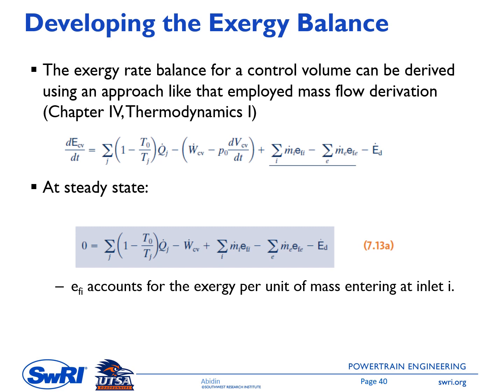on how the mass flow equation was derived. So here on the left side we have the exergy change of the system, normalized by time because this is in terms of rate. On the right side, the first term is the exergy transfer accompanying the heat transfer. Then we have the exergy transfer accompanying the work. And this one is the new parameter: the exergy flow accompanying the mass. Because it is a control volume, the mass can flow across the boundary. And the last term represents the exergy destruction.